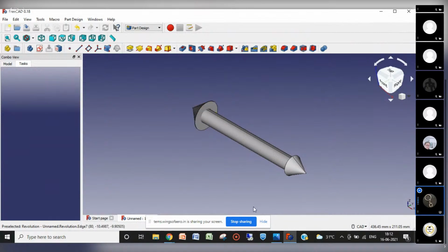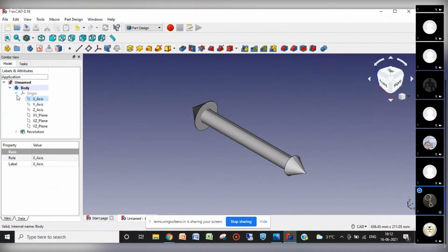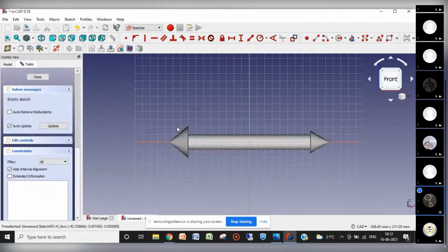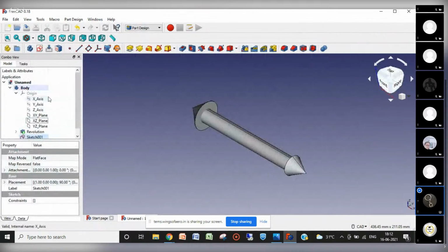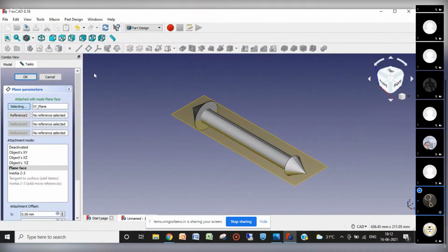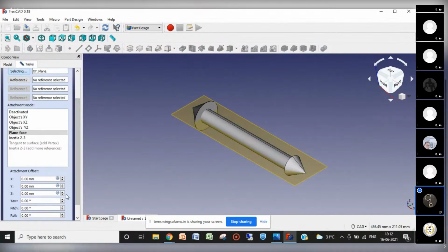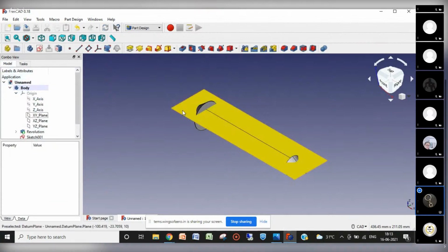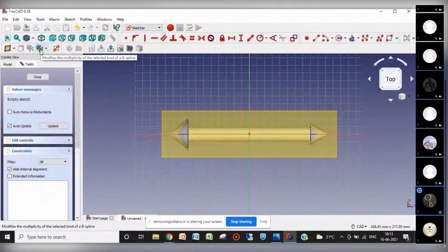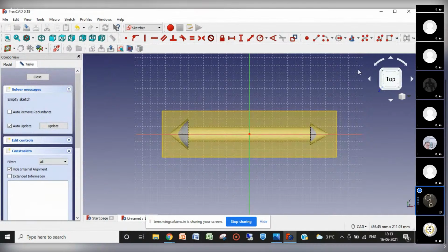Okay. So first we will make our propeller here. For the propeller also we will need the same plane, that is by XZ plane. Here we need a propeller. So I am taking XY plane and a datum plane about this plane at the height of, yeah, this 10 would be enough. Okay, selecting this plane and sketch over it.